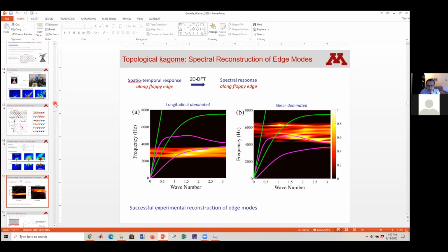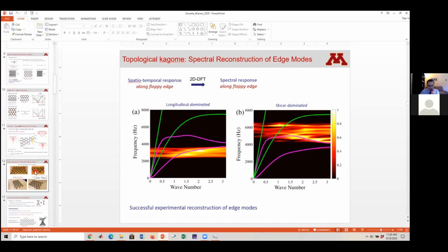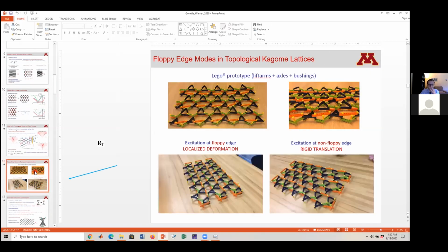And the comment that I have is that what you're talking about, floppy and rigid, we in structures call stability or geometric invariance. So yes, you have mechanisms on the floppy side and you don't have them on the rigid side. So that's what it is. It's insufficient connection between the members of the lattice.